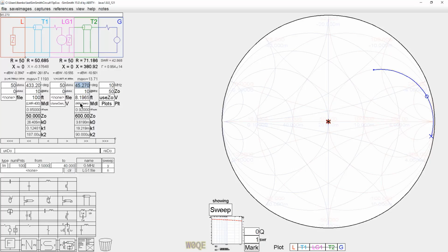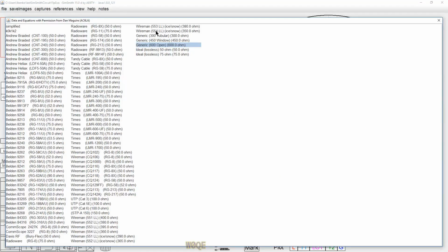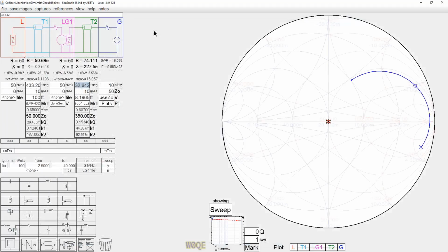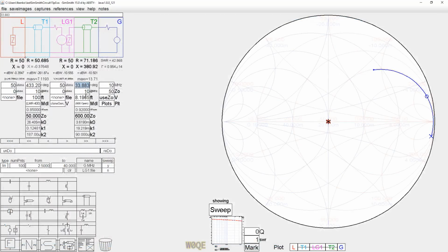It's either 14 or 12 gauge open wire line, but it's got a 92% velocity factor, which is higher than window line is. The window line examples here have velocity factors usually at 0.91 or something, 0.887 for that one. So we're going to use this one. This is probably about as good as it gets, unless somebody wanted to be pretty ridiculous in what they were doing. We'll set it to be 100 feet also.